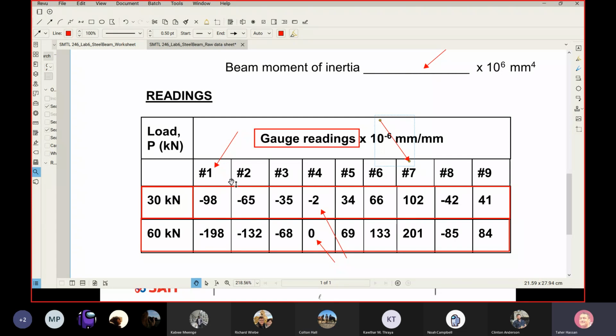By the way, this was my next discussion. You can see here there is a negative number. Any time you see a negative number, it means this is a compression. Any time you see a positive number, this means tension. But in theory, the 102 and the 98 are supposed to match. Why are we getting a four-unit error? This is measurement error.